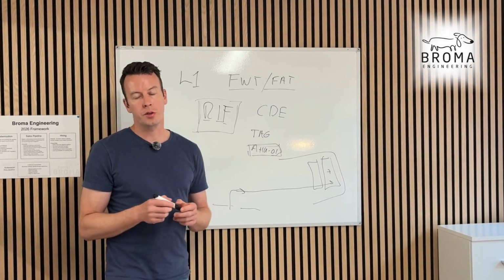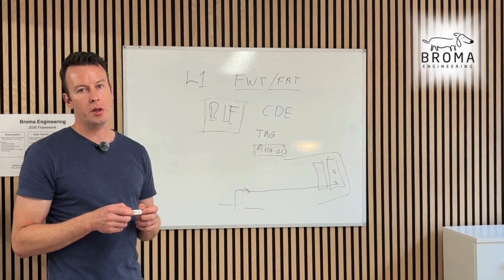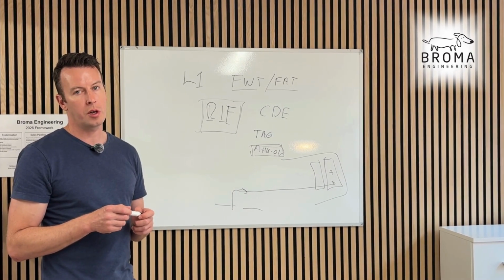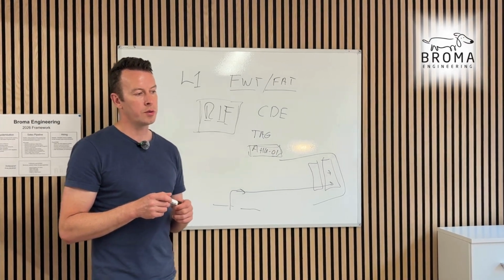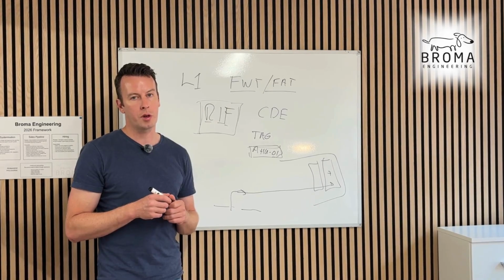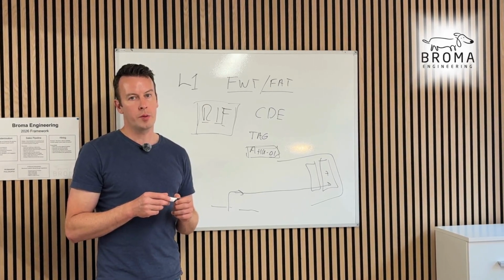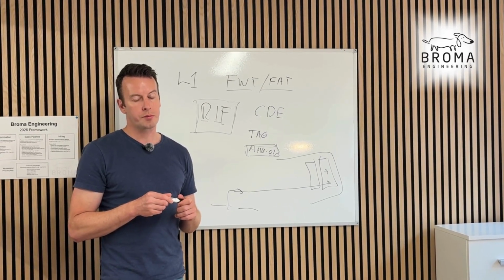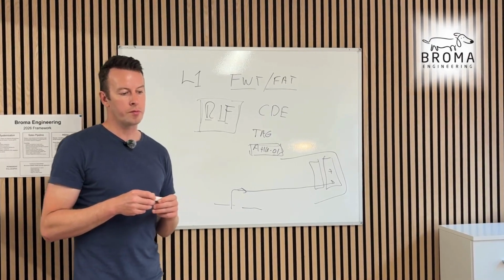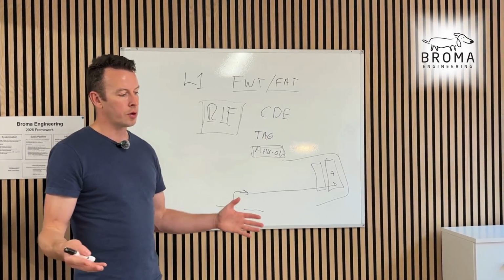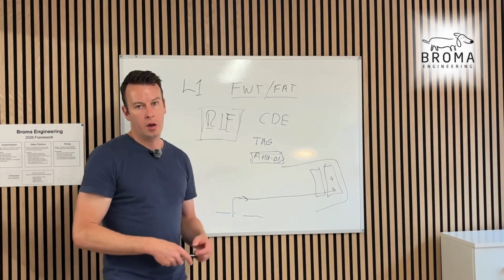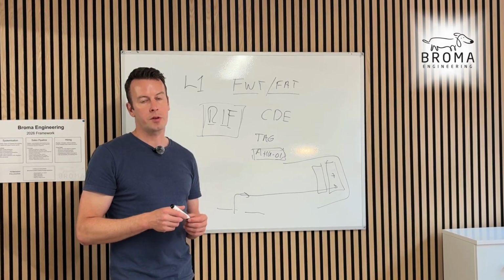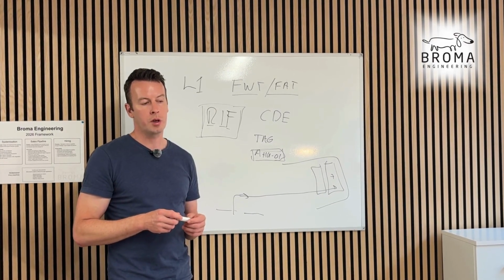Some AHUs are so big that they come in sections and they might have to be assembled outside before they're rolled in, and you might need a crane to lift sections up on top of each other. So make sure that's accounted for in your logistics plan. And then we're going to roll it in. You might need to build a concrete plinth to sit them down on and roll them one direction, then roll them another. You'll need a specialized heavy lift and shift contractor to do this usually.